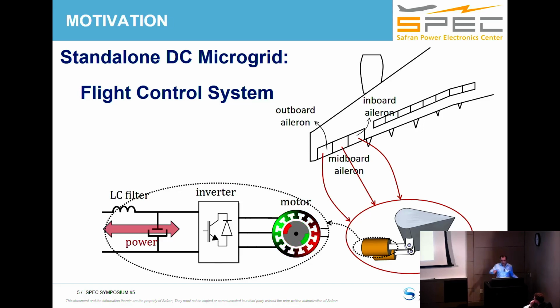At this stage, the idea is to have one electrified actuator, and the other one is mechanical. For the second aileron, you have one mechanical and the other one is hydraulic. And for the last one, they combine different energy types for each aileron in such a way to make the system more reliable.